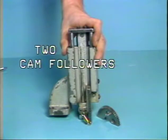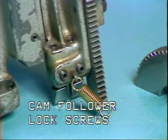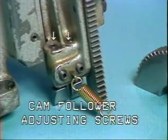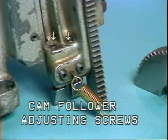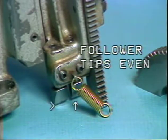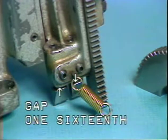Located here are the 2 cam followers. This is the cam follower for the first feed cam and the cam follower for the second feed cam or return cam. These are the cam follower lock screws. The cam follower lock screws are loosened to adjust each follower or to remove a cam follower. These are the cam follower adjusting screws. They are used to position the cam followers. Operation and adjustment of the cam followers are the same as with the 2-to-1 attachment. The follower tips are adjusted to be even, and the gap above the followers is adjusted to be not more than 1/16 of an inch.